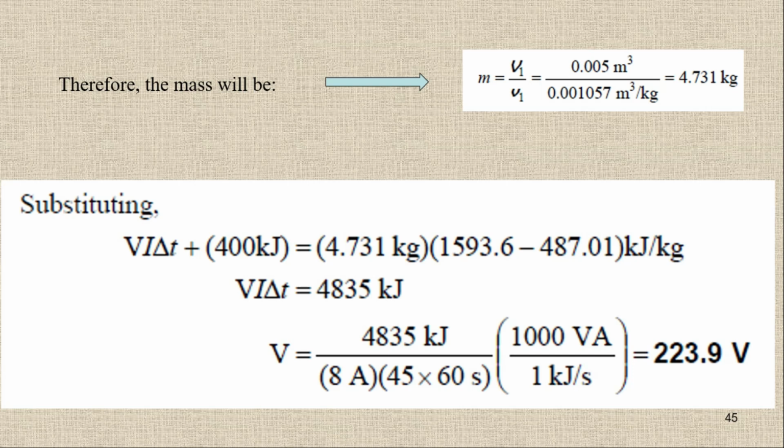The energy balance or the energy analysis basically depends on how you apply the equation. The energy balance is simple. We have the energy in minus energy out equal to delta E system. You have to check the energy values that are coming in, then the energies that are going out from the system, and within the system we have only internal energy change, because in most cases the systems are stationary, so there is no delta kinetic energy and delta potential energy.